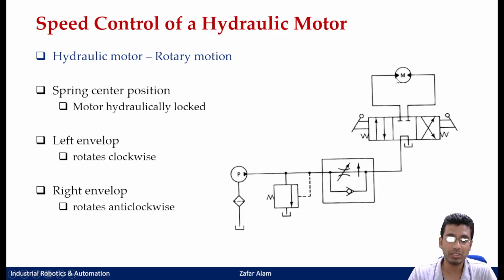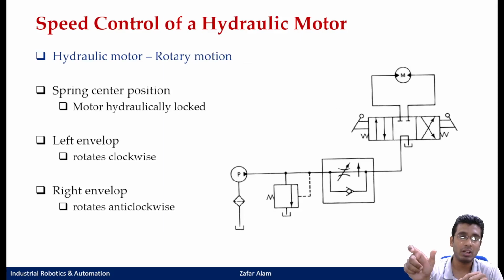that is generally required if you are extending a cylinder and retracting a cylinder. Say in the extension you require the motion to get controlled, but during the retraction you do not want the linear actuator to have any flow control mechanism. So in the retraction case, what would happen? Your circuit, if you see, would just go and take this path. Why? This is the easiest path. Since this is the constricted path, it will have free flow from this side and just drain out.